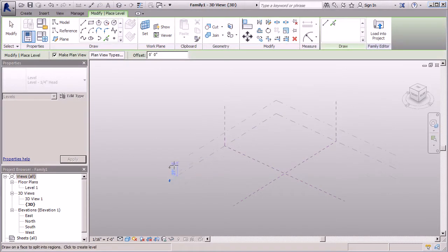Working with levels in this view is very easy because you're not worried about any start or end points. You're simply letting Revit know what the distance is. The start and end points on your elevation or level line is already set in place for you. So I know that I want 8 levels, so I found it really quick to simply place my cursor here at many levels above that I know what I'm going to be at. And I can simply type in my values and hit enter several times until I get to the 8th floor.